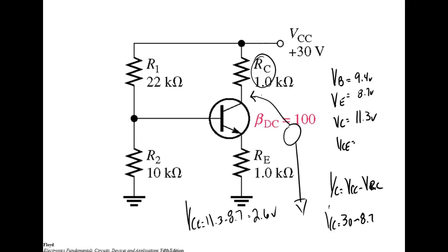Yeah, so if I've got 30 volts, that means the maximum I could possibly get out, and I'll never get that, is 30 volts. The minimum I can get out is 0 volts. So what I would like to do is bias it right here at 15 volts. That way, when my output swings, it can swing up just as high as it swings down. If it swings above here, then the transistor cuts off. We can't get more than 30 volts out. If it swings down and goes past zero, we can't get past zero, because the transistor is saturated, right? You understand that?